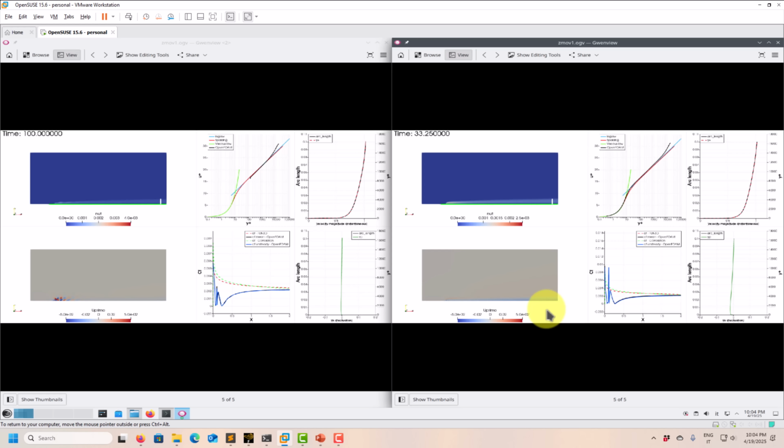Usually the best monitor is forces, but not always you are monitoring forces. Can be any quantity. And see here that maybe at this point, at 40 seconds, maybe you have both of them matching, they are not changing, or in particular, the mean value is not changing anymore. So maybe this can be a good moment to stop your simulation. Who knows? There are no more fluctuations here, okay? Who knows? Okay, but it's up to you, and you need to monitor that.